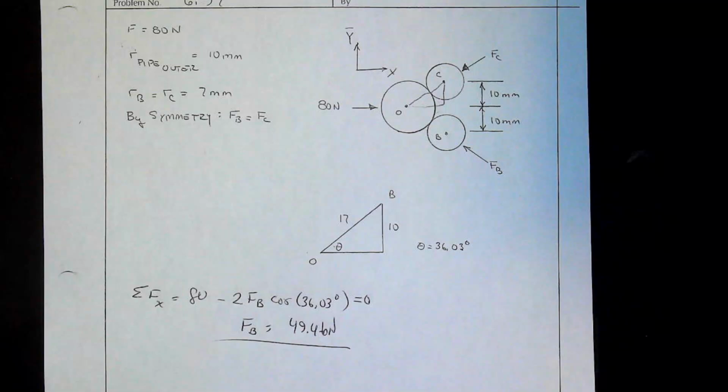Summing forces in the x, we would have minus 2512 cos 60 and minus 3076 cos 45 plus FAD, set that equal to 0. FAD equals 3431.72 pounds. And there's the end of the problem. So, really quick problem to pull off, though the picture, to start, kind of looks kind of ugly. All right.